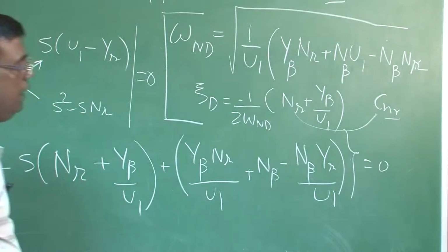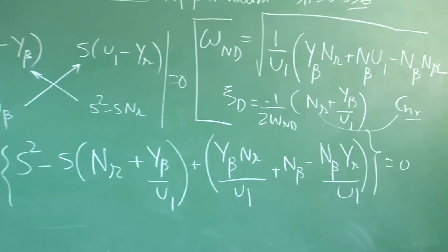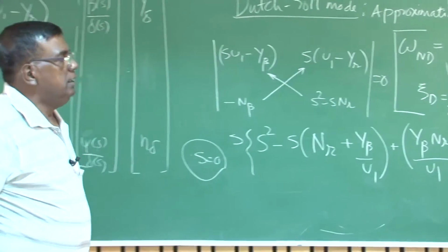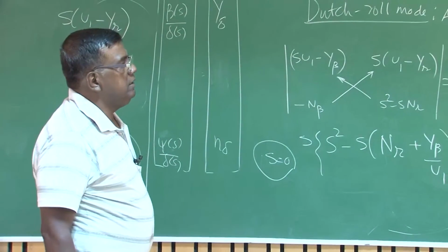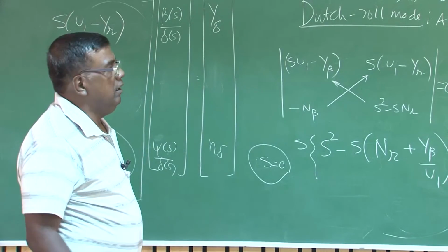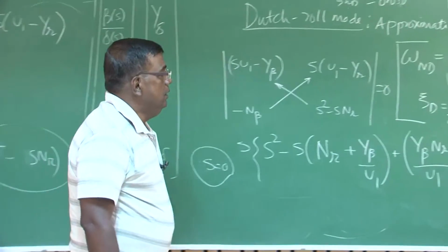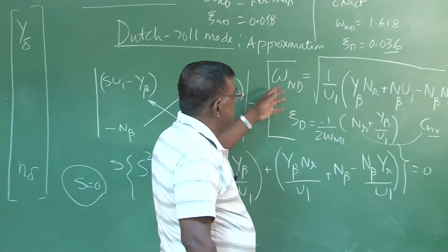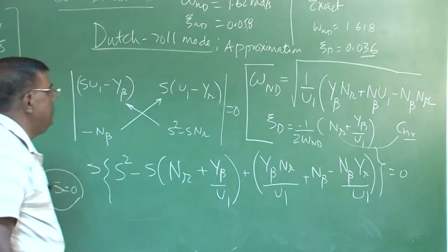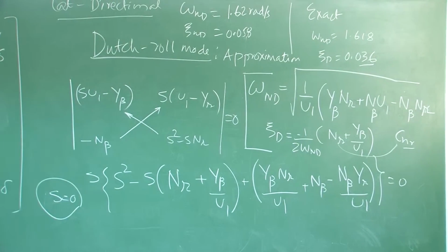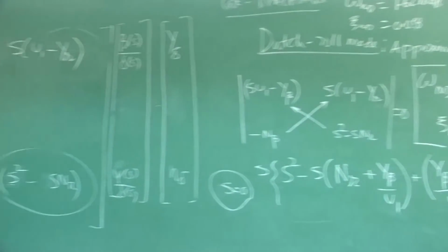And how CNR can be changed by either changing the distance from the vertical tail aerodynamic center to the CG, or the area of the vertical tail, or the tail volume ratio of the vertical tail. To have those ideas, I thought we must complete this before you jump into the stability augmentation system. Right? Thank you very much.